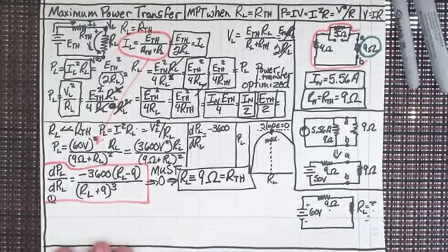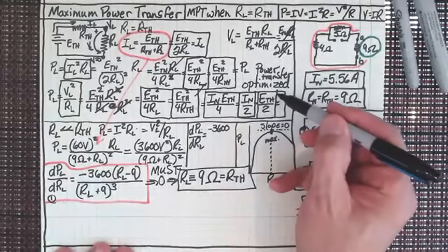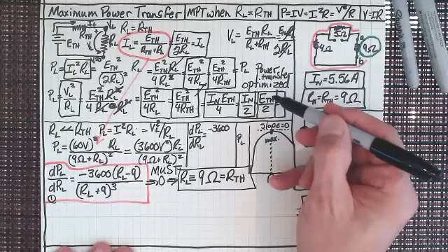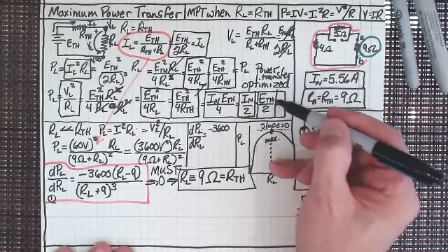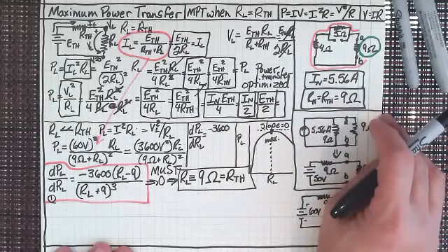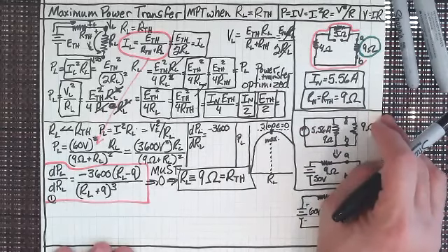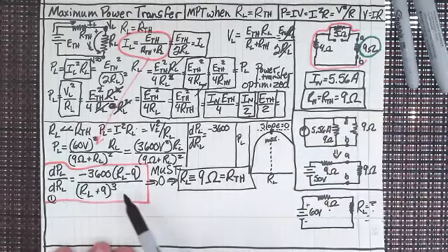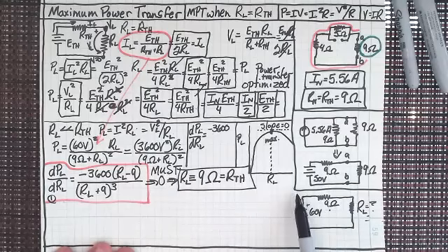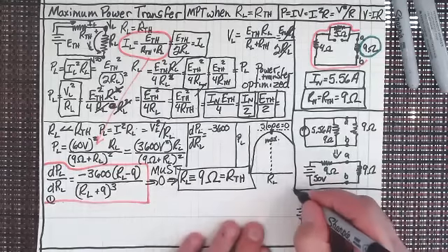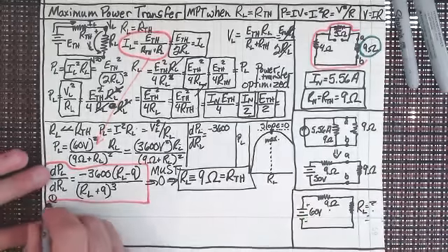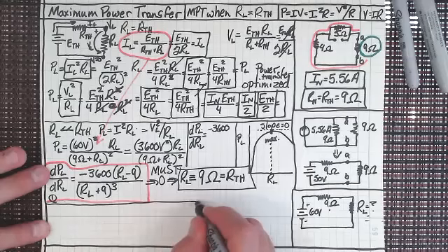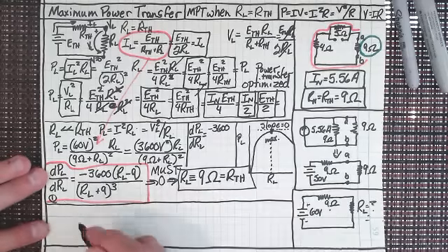And you find that maximum power occurs when the voltage is 1/2 and the current is 1/2 of what you would consider it to be for the Thevenin circuit. All right? Does everyone see why maximum power transfer now? And this is good. Now don't live and die by the fact that the load resistance has to be exact. This is a ballpark figure.